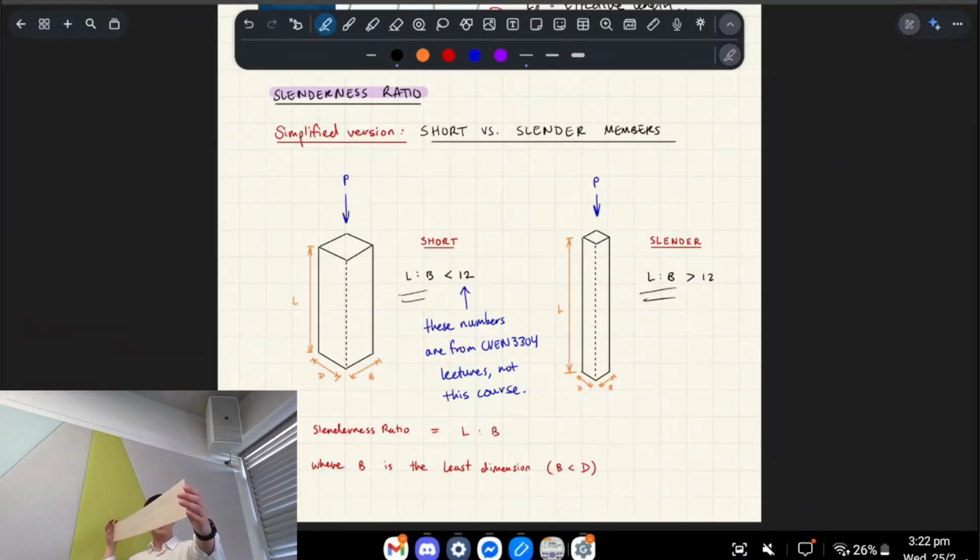No. So you have to keep in mind that when you have a cross section that isn't symmetrical in both directions, like when you rotate it 90 degrees, like this square, it can buckle out. Oh, sorry, it's not more likely. It will buckle out in the direction that's significantly weaker. So the minor axis, right? So the major axis, remember, is this depth, which is really high. But the minor axis is the one that's weaker, right? So it goes left to right.